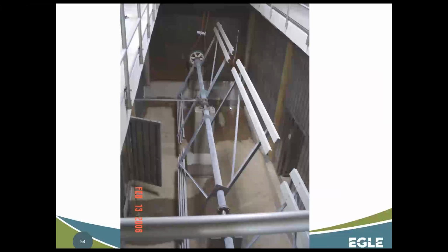Here's an image of an actual flocculation basin. You can see here again, they could add additional boards on here. This one is a chain drive. So you can see the sprocket chain. It's going up to a drive motor up here. Sometimes that's why you might want to use different numbers of boards on them, is maybe you have the same drive. So it gives you the ability to be spinning it at the same rate, but have different amounts of mixing energy. Down here in the basin, you can see there's some doors, people doors.